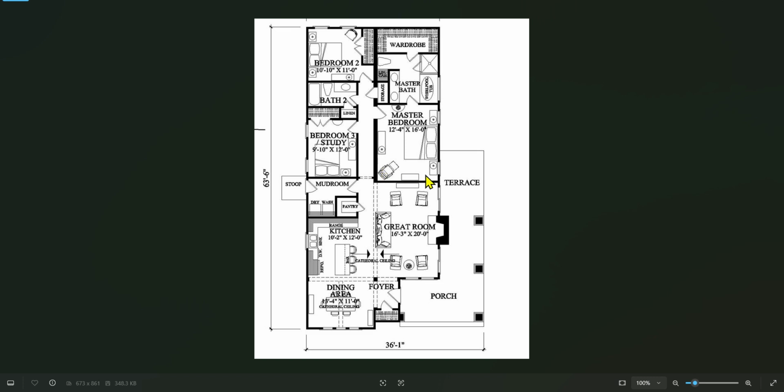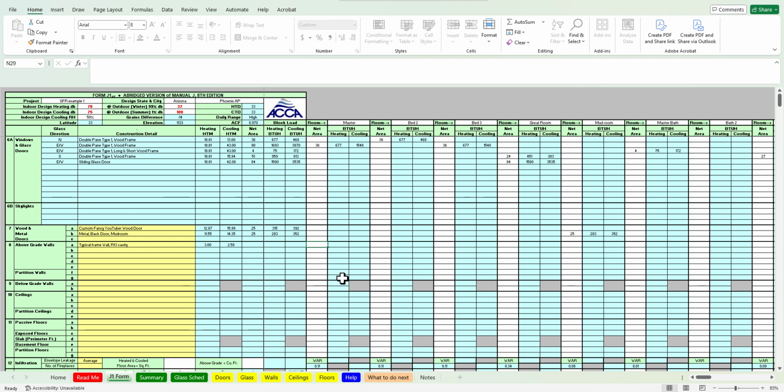Again, we don't care about the interior walls. It says it's 12.4 by 16. So 16 is this length dimension right here, and we're going to assume that it's an 8-foot wall. You might say the exterior is a little bit taller than the inside. It's 8 feet on the inside. On the outside, it's probably a little bit more than that, but let's just leave it at 8. That's totally fine.